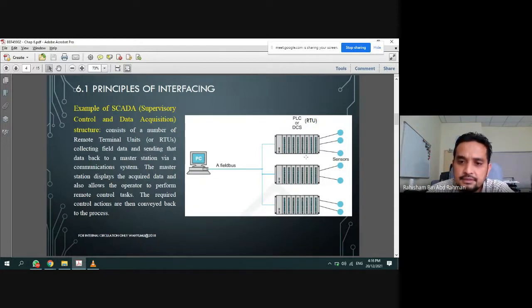task or operation. So SCADA is very powerful software to monitor, to save data, to control what is going on, and to acquire or plot the data of what is going on at the site. In fact, it can instruct what the valve or actuator should do at the site, whether to open or close by 5%, 30%, 70%. That is the capability of supervisory control and data acquisition, SCADA.